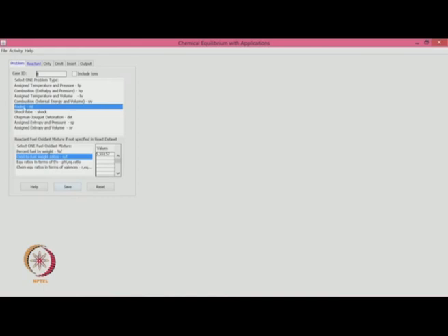Once you save this, because this is a liquid propellant problem, you have to define the oxidizer to fuel ratio, right. There are different ways to give that. One is equivalence ratio is also possible, then oxidizer to fuel ratio is possible, then percentage of fuel by weight is also possible. So, let us click on the oxidizer to fuel ratios. There is one set value that is given here, that is the value at which probably you will get the best performance. Okay. Now, let us also click other O by F ratios.